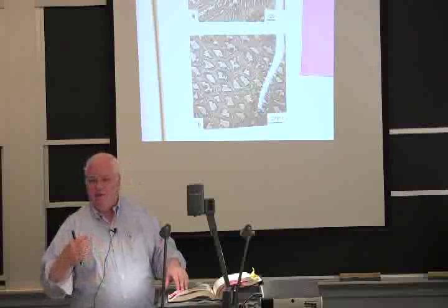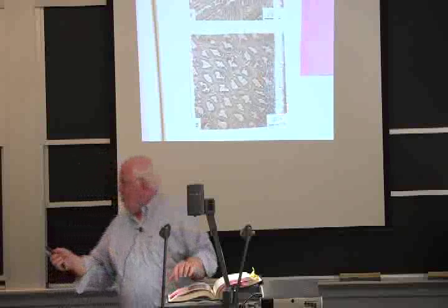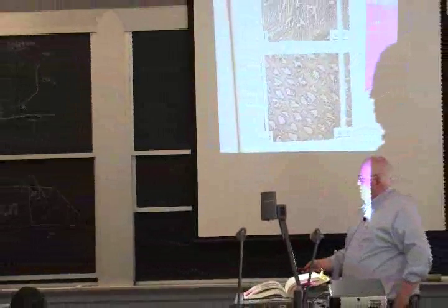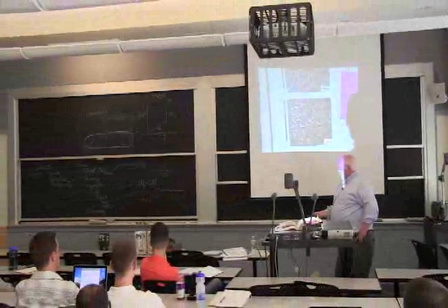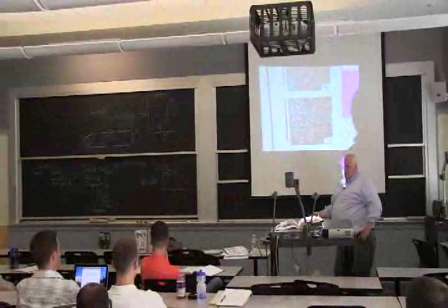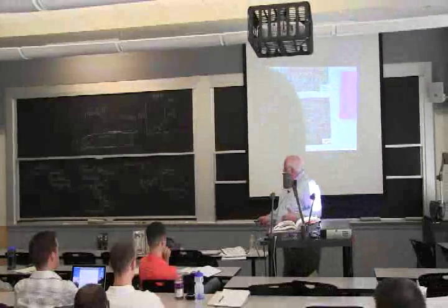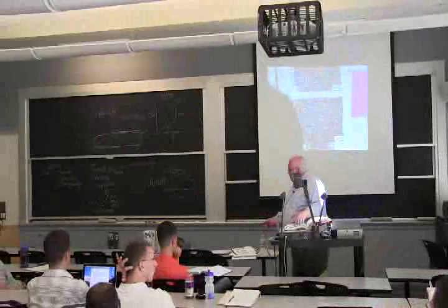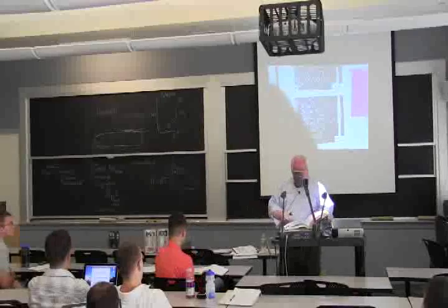On a microscopic scale, it's not uniform in concentration. So one of our goals was to get something that was homogeneous, and to control the structure. But depending on how we extract the heat of fusion, we can get very different structures. I'll show you some of those, and we can get segregation within the casting. Now, that can be on a micro scale like we see here, or it can be on a macro scale on the size of the whole casting.